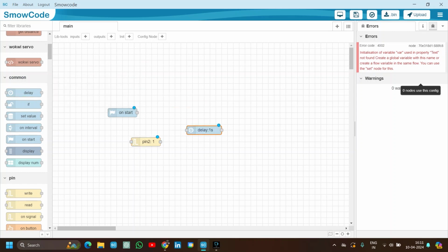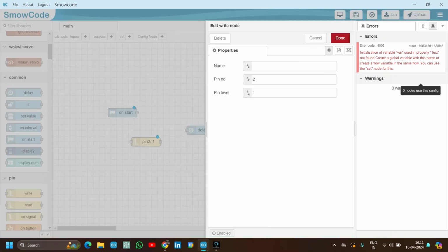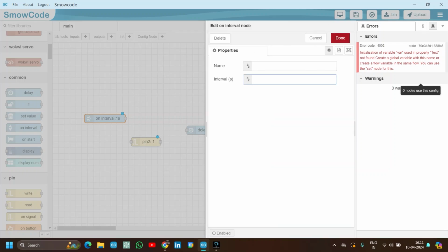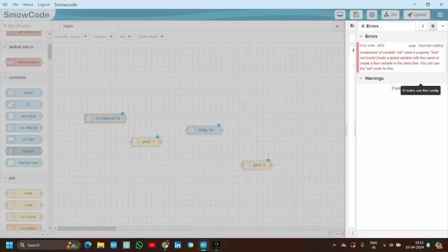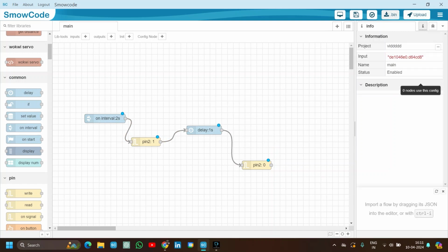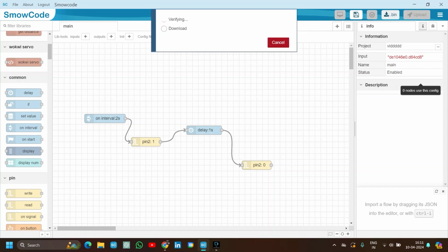use a delay, make a Blinky project, set the pin as 0, and print this. Then set the delay to last 2 seconds, connect it, and now if you don't have the hardware, you have to unplug the USB from your laptop and click on the .bin button.